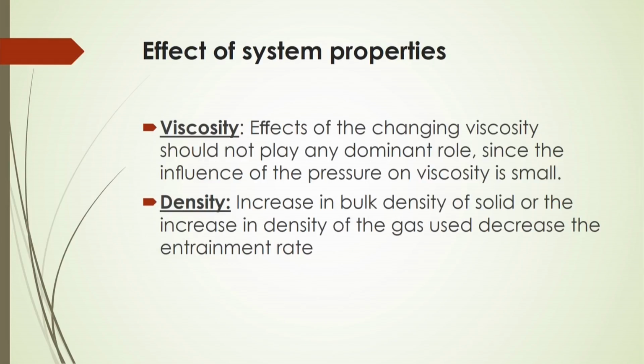Now, the effect of system properties. Of course, what are the system properties? Viscosity and density. Viscosity should not play any dominant role for entrainment in this gas-solid fluidization system, because air is mostly used, or some other gases whose viscosity is not that high compared to a liquid. So, there will be less effect there.